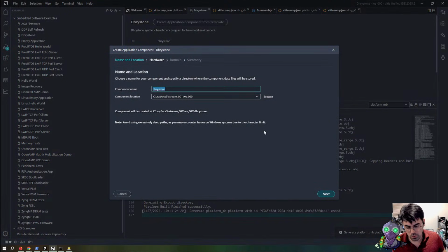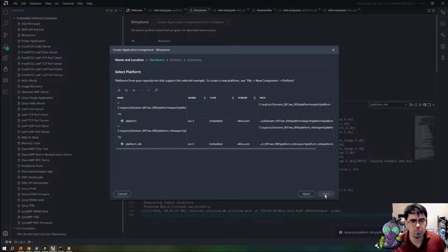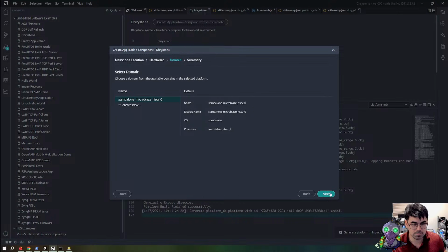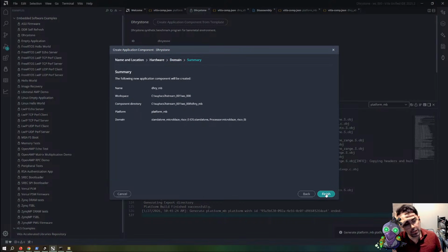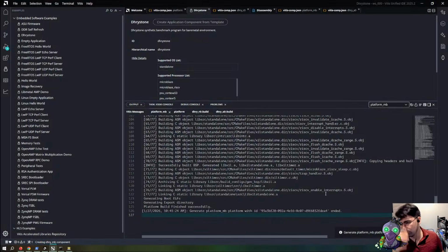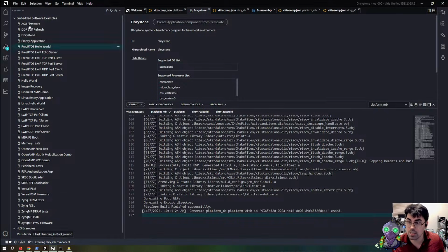Usually you would use your own PL-based, fabric-based UART, but there are ways to set up communication or a mailbox with the other processors and forward that data. But we're just going to use the JTAG for now. Okay, let that finish, and then we can run the MicroBlaze design.